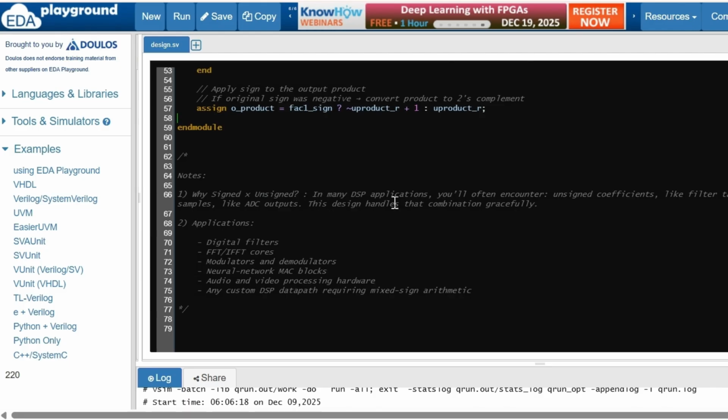So the ADC samples are signed, and then for the gain error correction, basically we multiply by gain and do the subtractions with the offset. Sometimes the gains are positive and the ADC samples are signed. So we have to multiply the signed numbers with an unsigned number, and in those kinds of applications we can implement the logic like this.